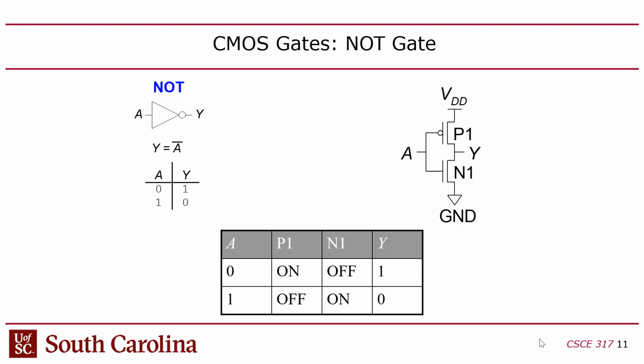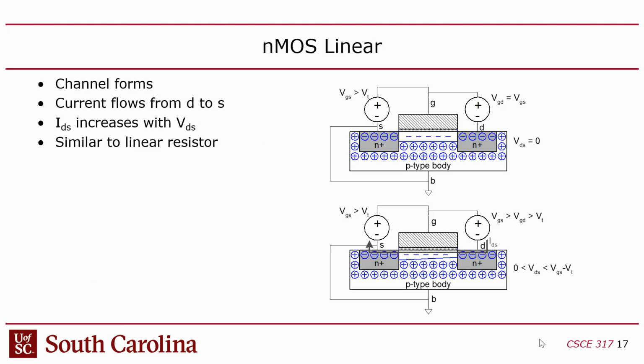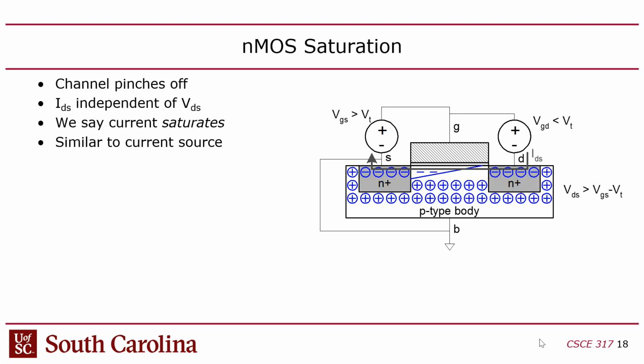So in steady state, generally you don't have that much drop over either one of these transistors. When you're pulling up or pulling down, usually you're not dropping a lot of voltage over either the pull down or the pull up. But when you first make that change, when you transition the state of the transistor, you will have a big drop initially. You'll ask a lot of these transistors in terms of the voltage difference right after you switch dynamically. So that's the problem, if you try to drop a lot of voltage over this guy.